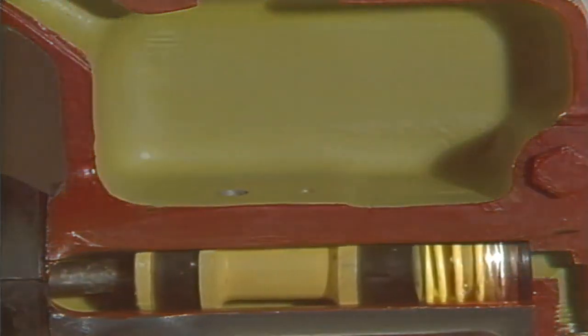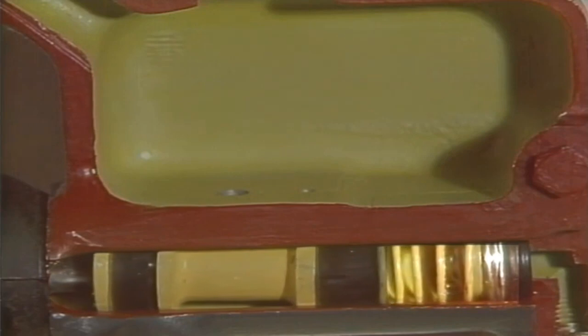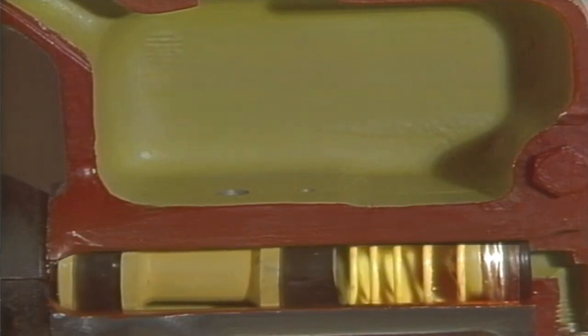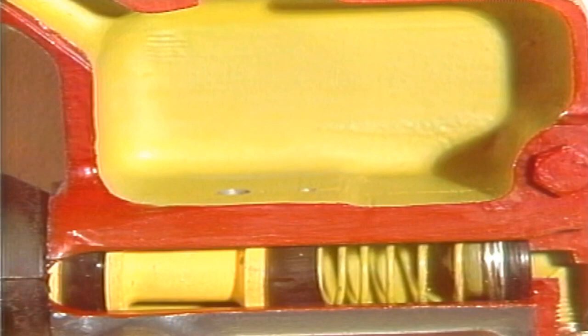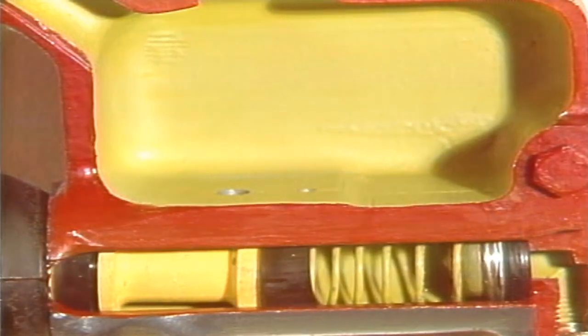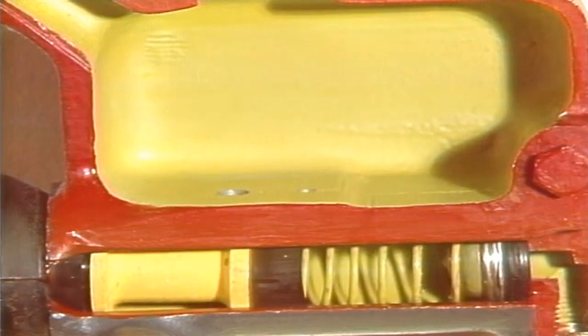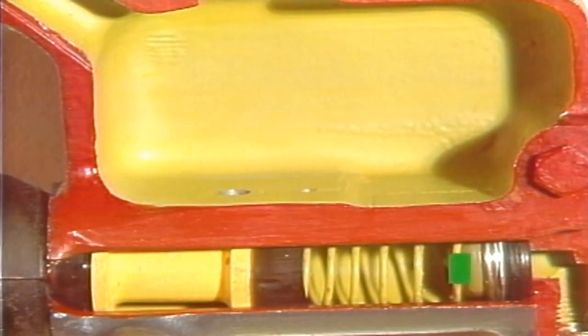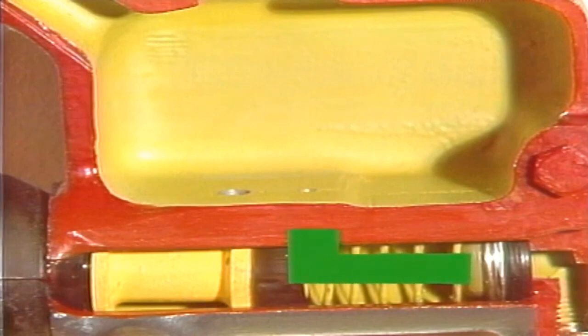The spring drives the piston and sealing cup backward, and so pressure forward of it and in the brake line drops. This brake line pressure bears against the residual pressure valve, tending to hold it open. But eventually, as brake line pressure decreases, the spring overcomes its force and reseats the residual pressure valve. This traps a small amount of pressure in the brake lines and wheel cylinders, and we'll see the effect of that later. As piston motion continues, the compensating port is reopened. Brake fluid flows back into the reservoir through this path.